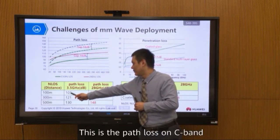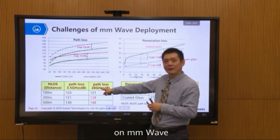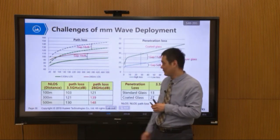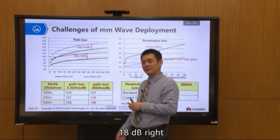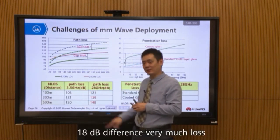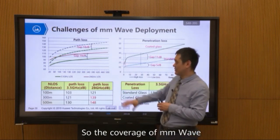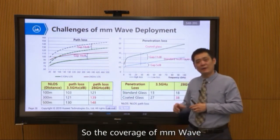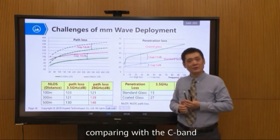This is the path loss on C-band, and this one is the path loss on MM wave. They have a great difference. 18 dB, right? This one, 18 dB difference. Very much loss. So the coverage of MM wave will be very weak comparing with the C-band.